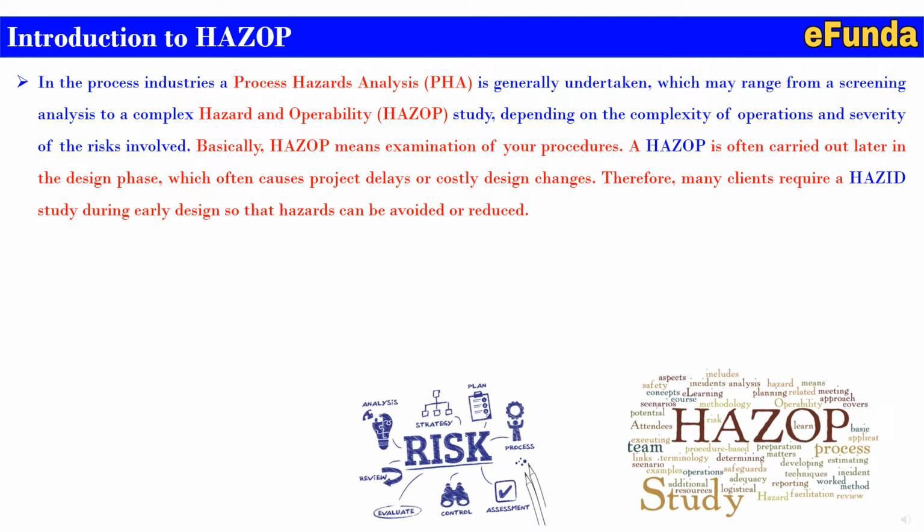Mainly, HAZOP concentrates on identifying both hazard as well as operability problems, while the HAZOP study is designed to identify hazards through a systematic approach. More than 80% of a study's recommendations are operability problems and are not in themselves hazards. Although hazard identification is the main focus, operability problems should be identified to the extent that they have the potential to lead to a process hazard, result in an environmental violation, or have a negative impact on profitability.